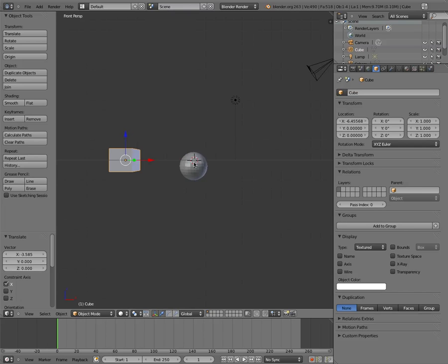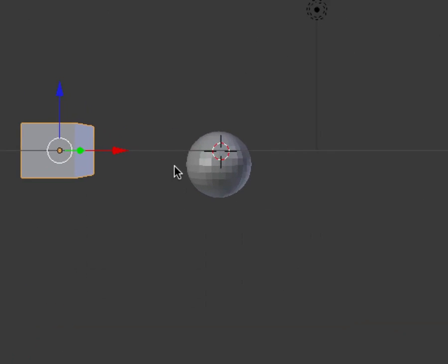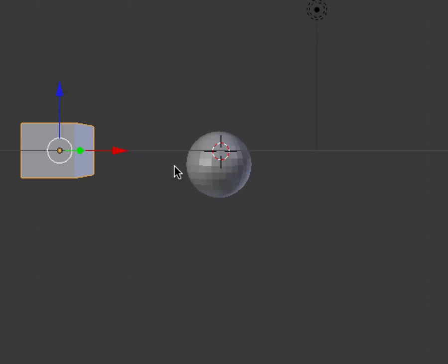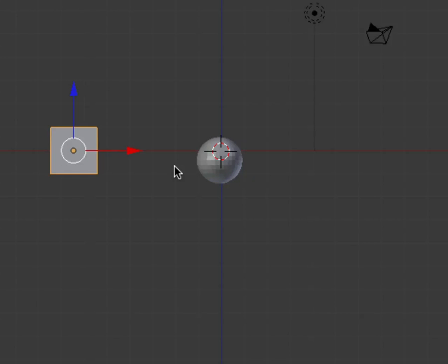Notice the other thing that I can do here, look carefully as I hit the 5 key. What happens, especially look at the cube. What am I turning on and off when I hit the 5 key? Yeah, James? They're right. I'm turning off my ability to see things in 3D. In other words, I'm turning off the perspective. So if I hit that 5 key in the middle of the number pad, I turn off the perspective.